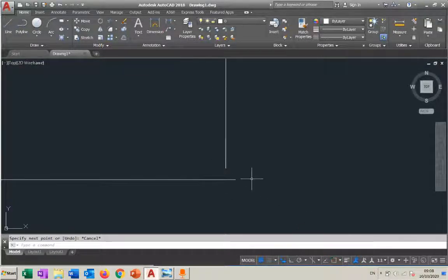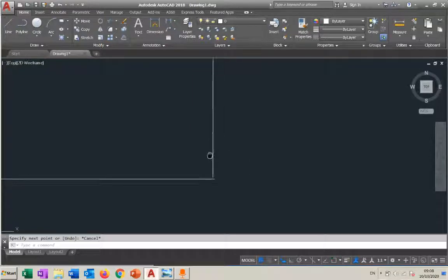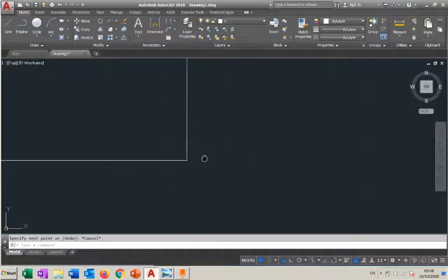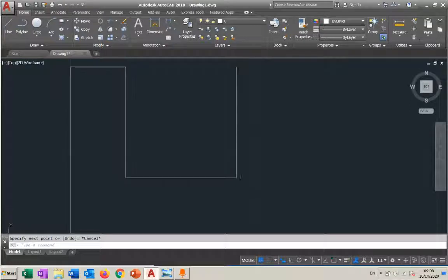This is one of the problems that I've seen with many students, that they don't know the benefit of object snap. So we said that in the beginning, make sure object snap is open. Why? Because later we can explain them in detail. So activate line. If I don't see any green things, I know who is responsible, object snap. I'll click on object snap. Then if I simply come close to the point, I can see the green square. I can just simply click there.